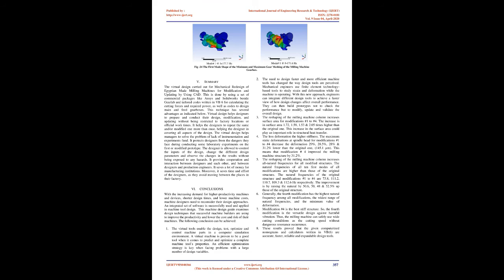Harmonic response analysis of the gearbox. The gearbox is exposed to defects in the gears or shafts due to varying magnitude loading. According to the previous calculations, a moment was applied as a boundary condition at the input shaft of each model of the main gearbox. Table 5 presents the natural frequencies, Hertz, of the gearbox with the probabilities 6 times 2, 4 times 3, and 3x2x2.